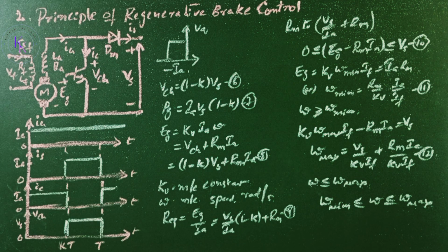Although DC series motors are traditionally used for traction applications due to their high starting torques, a series excited generator is unstable when working into a fixed voltage supply. Thus, for running on the traction supply, a separate excitation control is required, and such an arrangement of the series motor is normally sensitive to the supply voltage fluctuations, and a fast dynamic response is required to provide adequate brake control. The application of DC chopper allows the regenerative braking of the DC series motor due to its fast dynamic response.